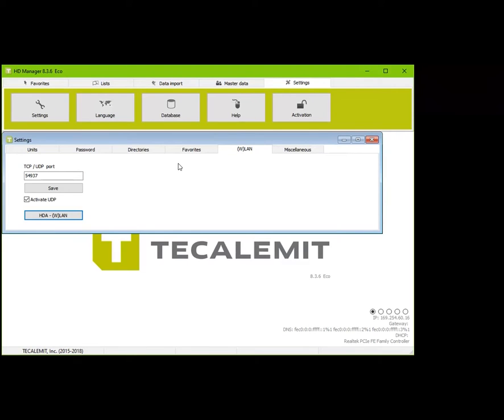On a Superbox, you're going to hit any top gray key and then the wrench. You're going to enter the 9 5 times, 99999, and hit enter. You're going to scroll down to menu interface and hit enter, and then you're going to scroll down to read config and hit enter. It's going to prompt you to plug in that USB stick, so you're going to go ahead and plug that in. It's going to go through some settings, and then it's going to return to that read config. Once it's done that, you can remove the stick and hit exit 2 times.